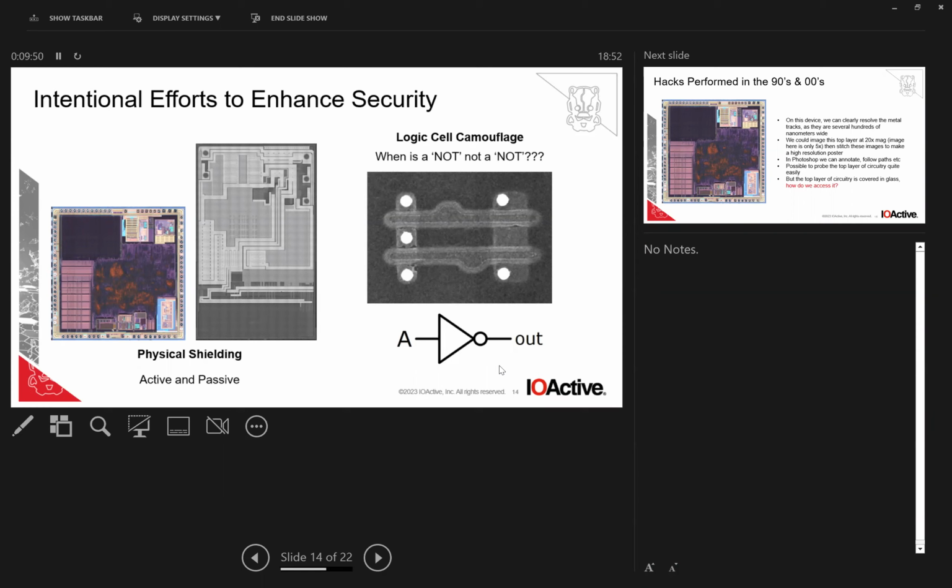Yeah, we need the SEM to take the pictures, of course, because you can't resolve them with optical microscopes anymore. And when it comes to doing an attack, like an extraction, you need a focused ion beam. That's why we call it a dual beam. You have the electron beam to look at things non-destructively, and you have an ion beam, which you can image with as well, but you can also cut holes and deposit material, both conductive and insulating material. So if you know what the device is doing and have the design in front of you, you can take a real chip, change that design, and make it do something it's not supposed to. And that's what people do basically.